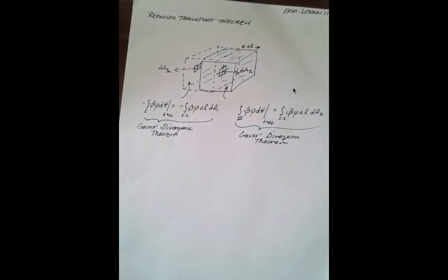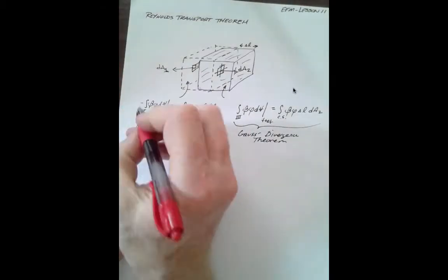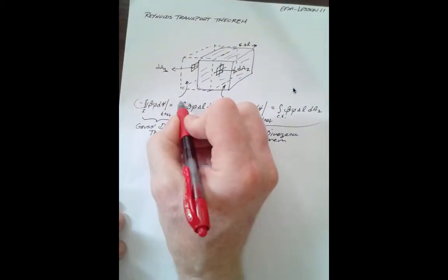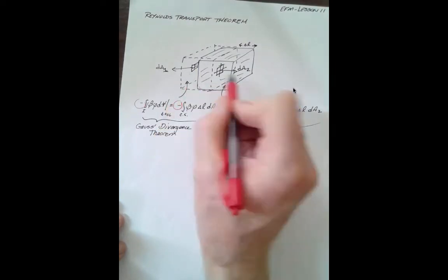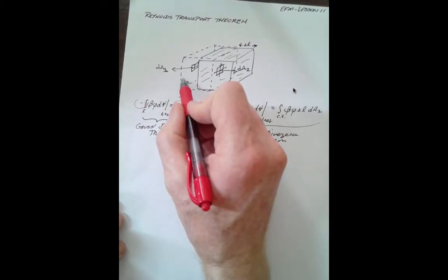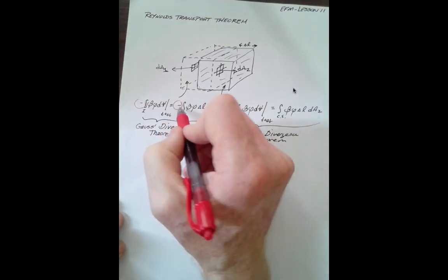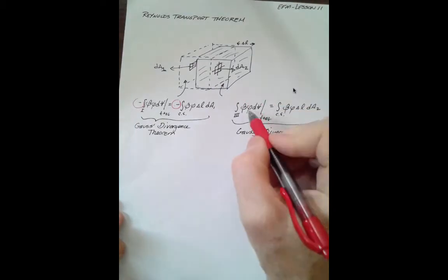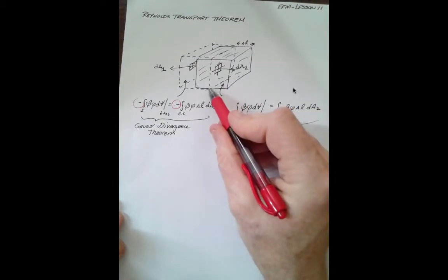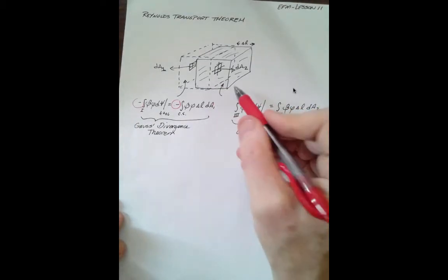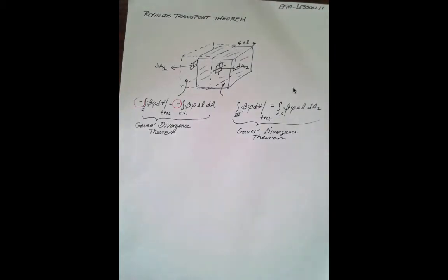Why is 1 minus and 1 not minus? This one's taking on the negative signs because we're evacuating the area. So there used to be mass there and now there isn't. So it's a negative quantity. Whereas out here in zone 3, there used to be nothing there and now there is something, so it's a positive quantity.